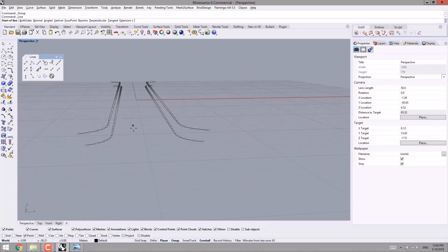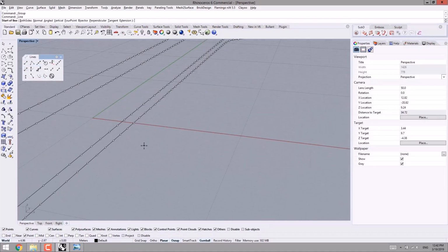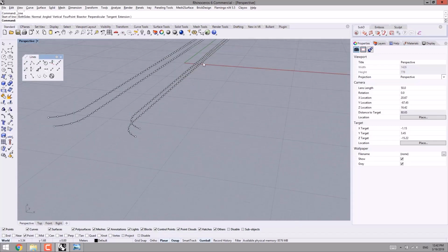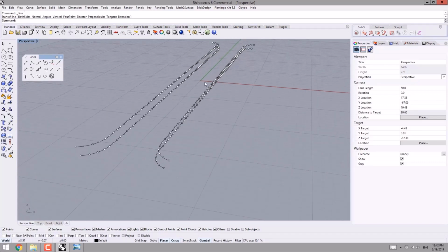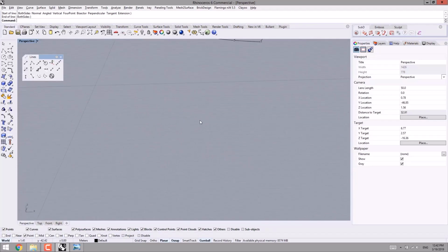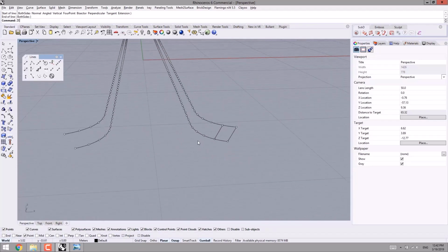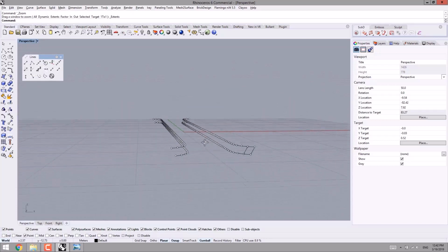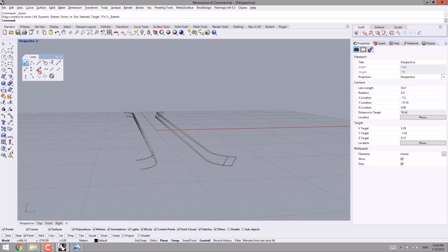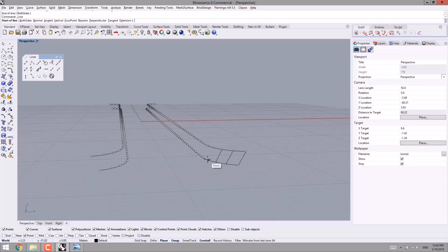Then I pick single line again. In the continuation, as you can see on the screen, I'm going to sketch the single lines, and after that, by using mirror, I can complete half of it, and then for the other half, I can use mirror. So let's start this way. I connect the points to each other by single line. I type ZE in the command line for zoom extents. Then I can observe the points better.